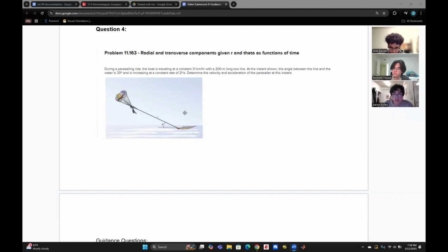To solve for its absolute velocity, we solve for velocity tangent prior. We know it's given because the question is asking for a given position. We know the angle that the velocity tangent is pointing at. If we treat this as a Cartesian coordinate system, we know its absolute direction. So we know that it's pointing at 60 degrees above the horizontal.